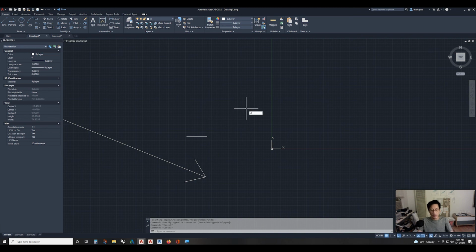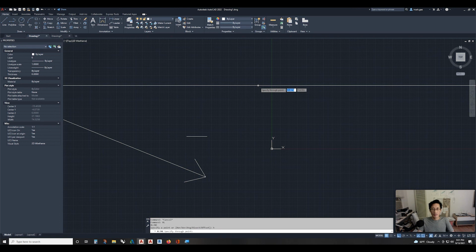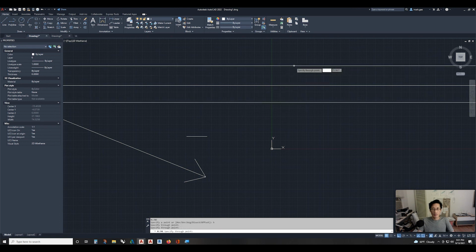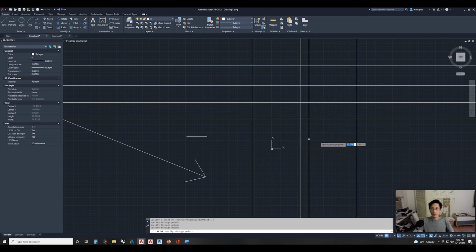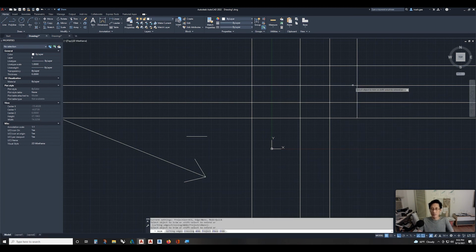So if we happen to have some horizontal X lines, and we also have some vertical X lines that we say we've used as guidelines for something, we can actually use these as lines in our final drawing as well, again, by editing them, to trim them, perhaps, to create actual line objects.